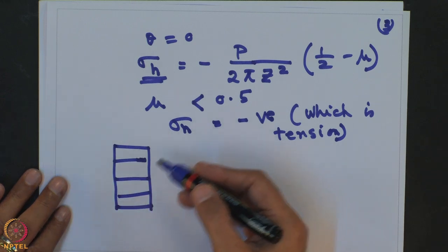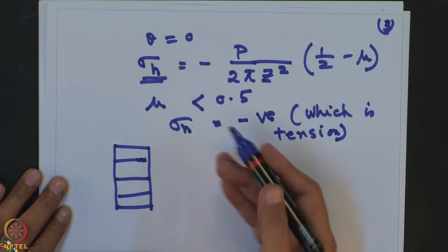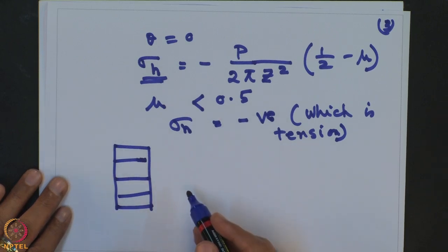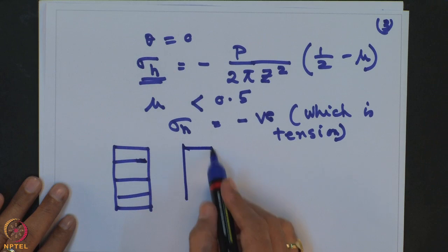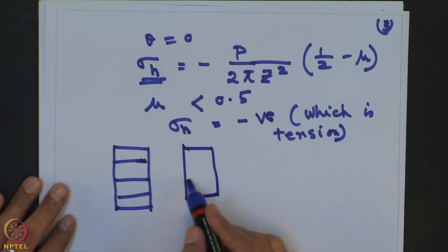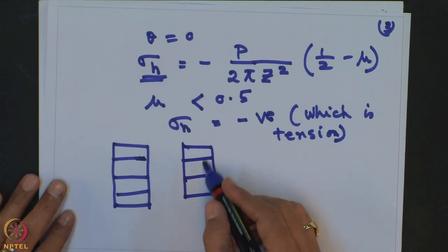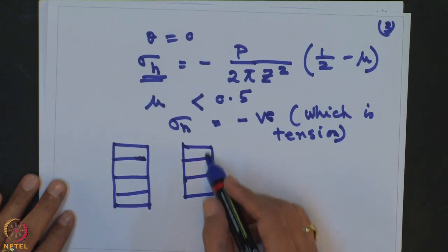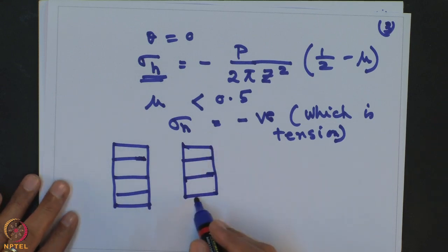So, whether you are placing it on very soft soil, there will be a yielding situation in this particular reinforcement mechanism. And if you place the geotextile material at a distance in between, so that a spacing is defined between the two geotextile layers, then you find the tensile strength required is on the lower side.